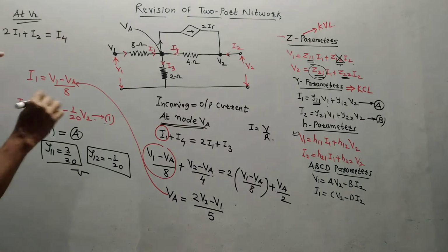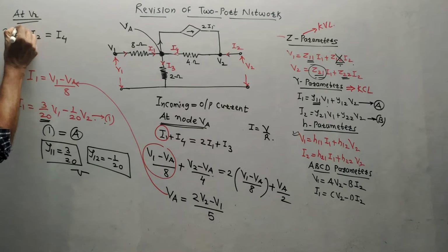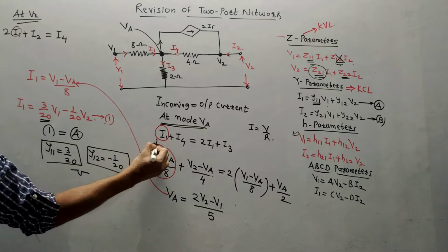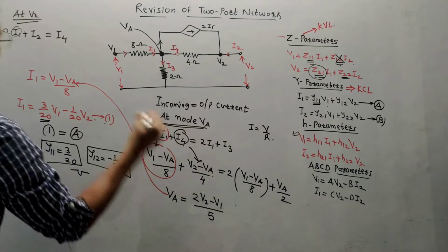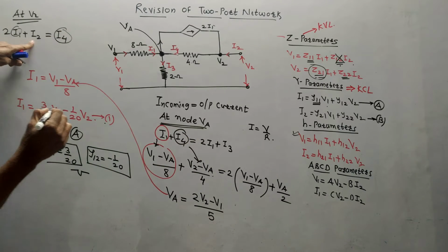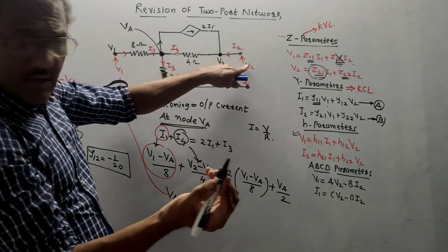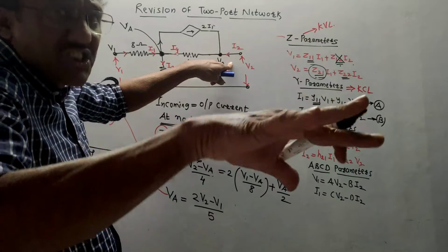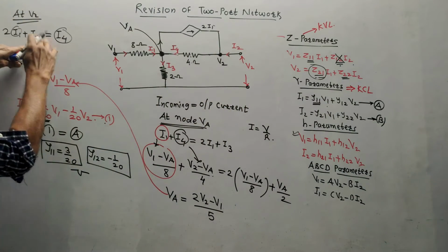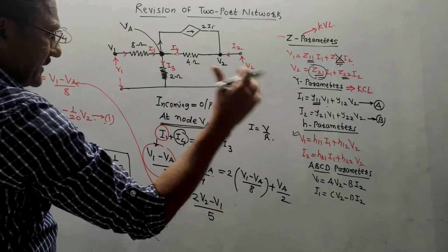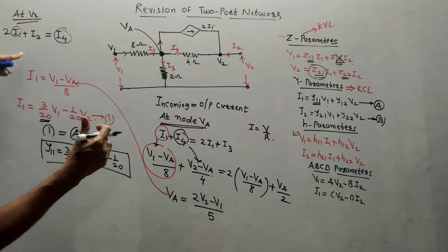Again, same technique. We have already all the equations which we have written. Put the value of I1, this value. Then we have written the equation of I4, this is the equation of I4. Again, put the value of I4. I don't have the equation of I2, let us develop it. Look at the diagram. There is no resistance. So in such cases, how to avoid the condition? There is no resistance, so I will keep I2 as it is, because later on I can simplify it using any technique. So I am keeping this term as it is.